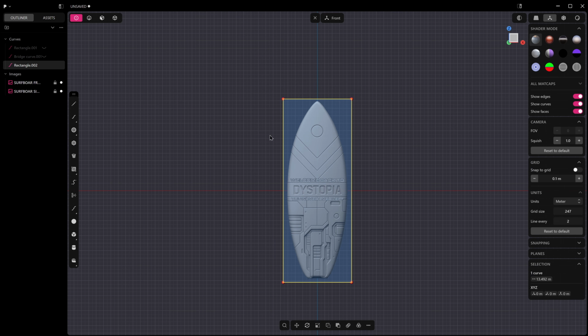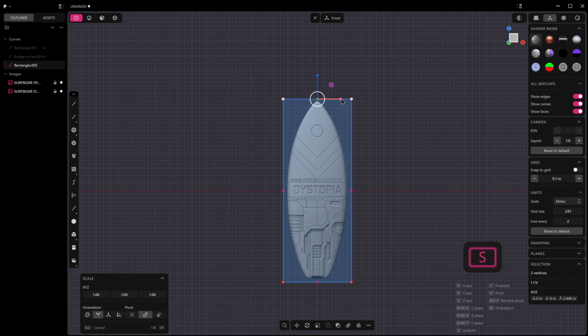Now we want a little bit more to be able to build up this shape, so I'm going to press Shift and S. Okay, and this subdivides it, so we've got now 3 across the top and 3 across the side. So what we're going to do is just select these ones at the top with our marquee, and I'm going to press scale, and I'm going to scale that right in. I'm going to take these ones in the middle, I'm going to scale them out.